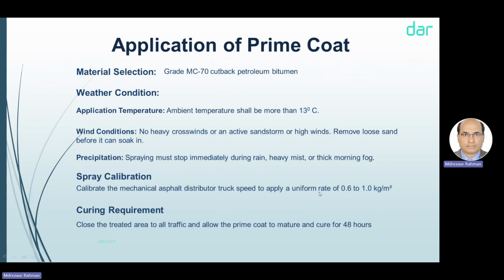Then all equipment must be calibrated. We have to check one day before that all machineries are available and calibrated. Without calibration, they are not allowed to start any equipment. And after the prime coat, there should be 48 hours to cure. Before 48 hours, the contractor cannot start.